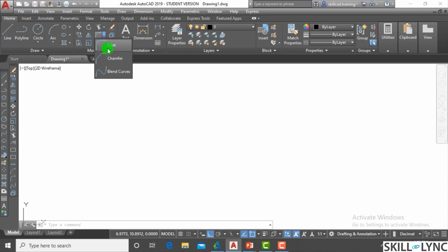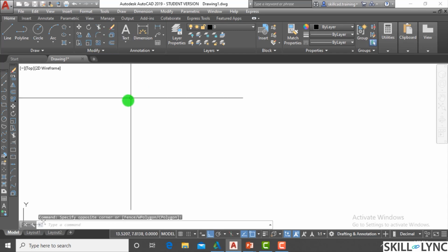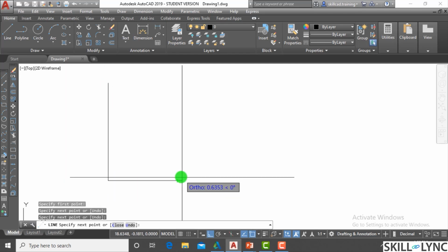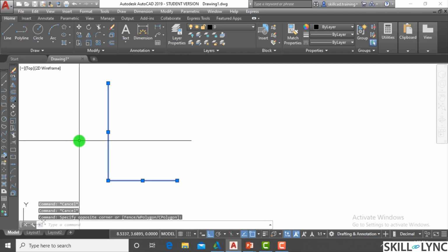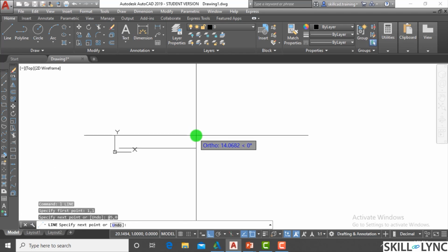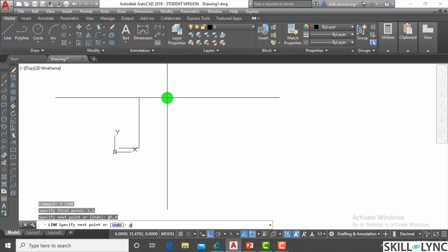So we have a fillet option. You can see there's a curve over here. So let's see how it works. Go for a length or a line option. Let me create a line, of a length, in fact. So let's say I start from 1,1, and at the rate, let's say 5 units, right? Because you have learned it quite well, how to create lines by coordinate systems.